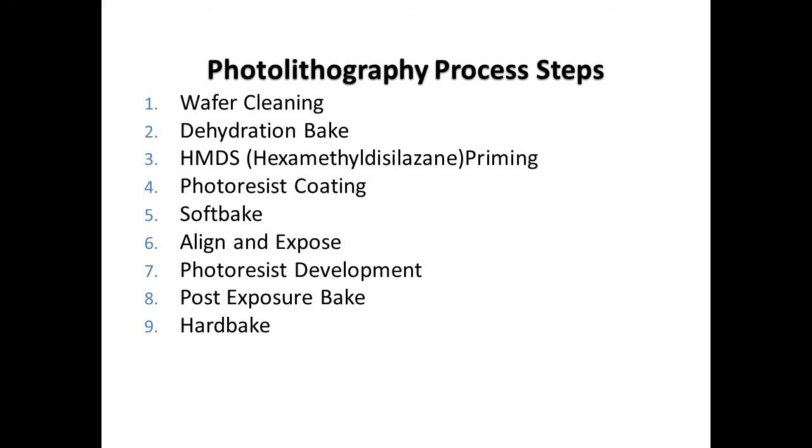And then you have the development. This development also needs skills, because like I told you, it depends on the type of photoresist you are using, and also the thickness of the photoresist. If the photoresist is thicker, you need more time to develop it. If it is thinner, you need less time. It can be not more than 5 seconds to process it, and sometimes it takes more, depending on what type of photoresist you are going to use.